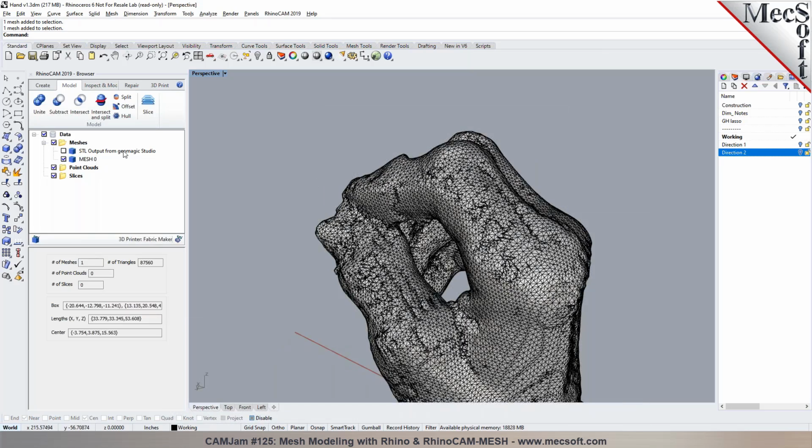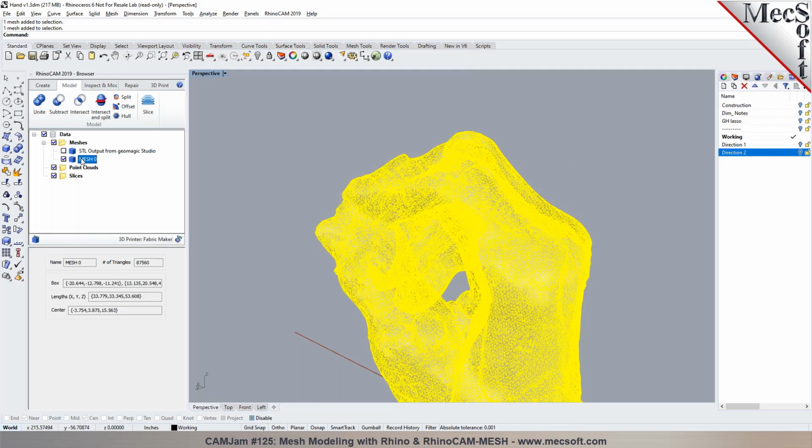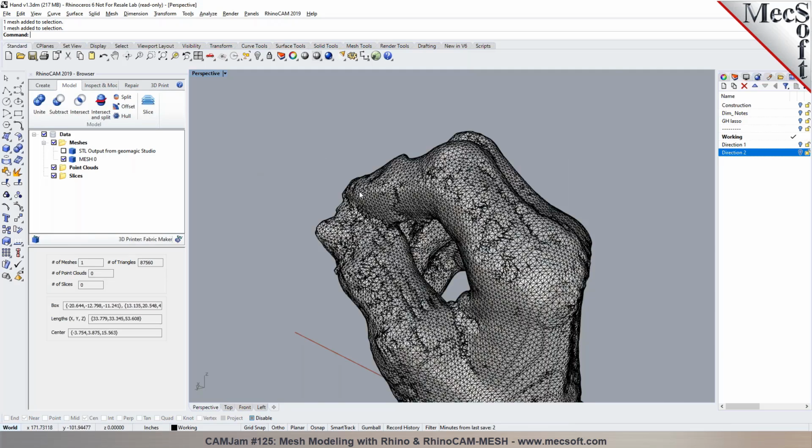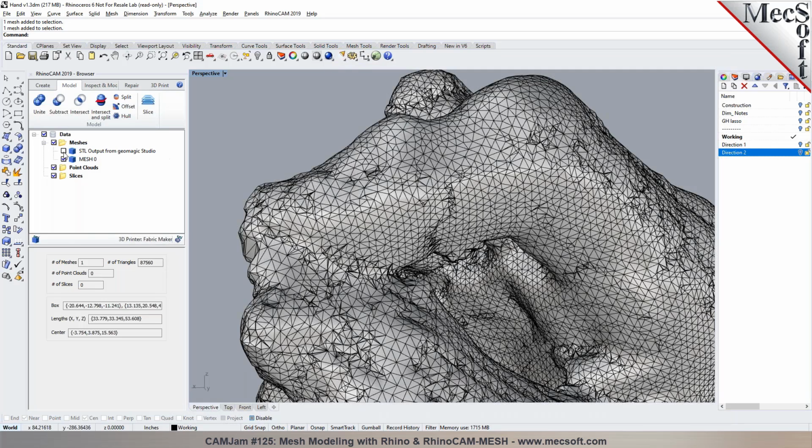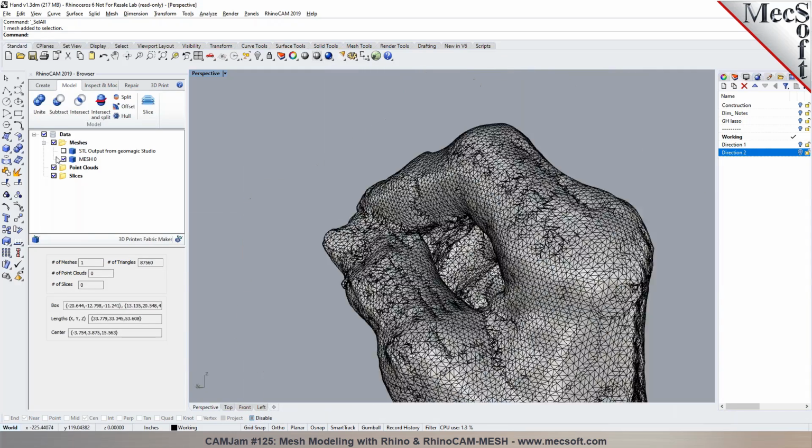The thickness STL is the one that you provided, the one that came in from your system. And then the mesh is what we represent in the tree. So that's the mesh geometry. So I've hidden the STL, as you can see right here. I can toggle the display of it. So right now there's only one mesh that's showing, which is already offset. So if I hide this one, you can see the original one, and there's your offset.